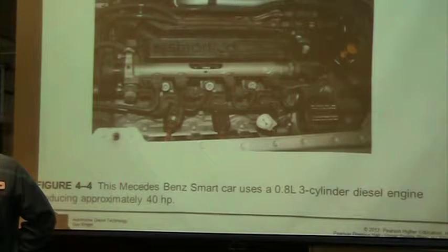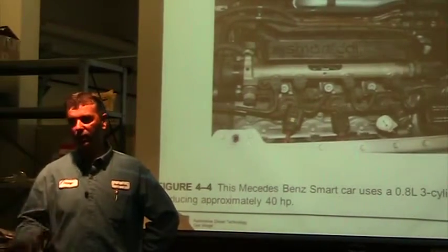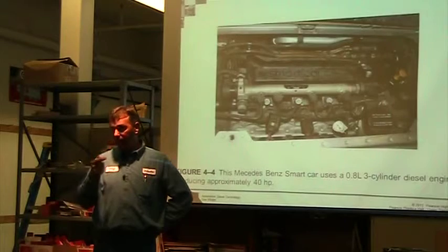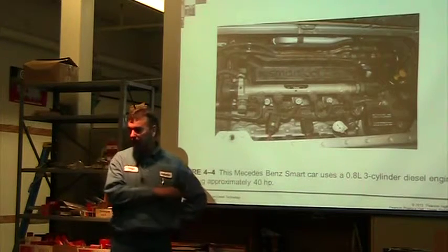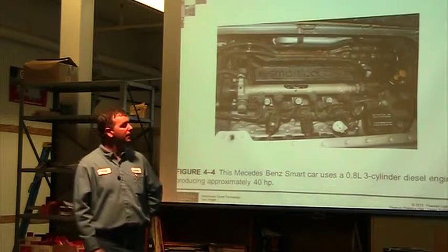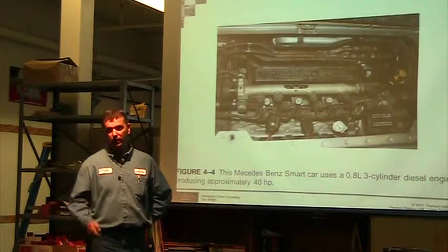So you put a filter in, you bleed it to the top, and then you start it up, and you can tell when all of a sudden the bubbles are gone. Right. If I had a line with a crack in it or something and I'm seeing bubbles in it, I could go find that problem. So it's just a nice built-in way of troubleshooting.